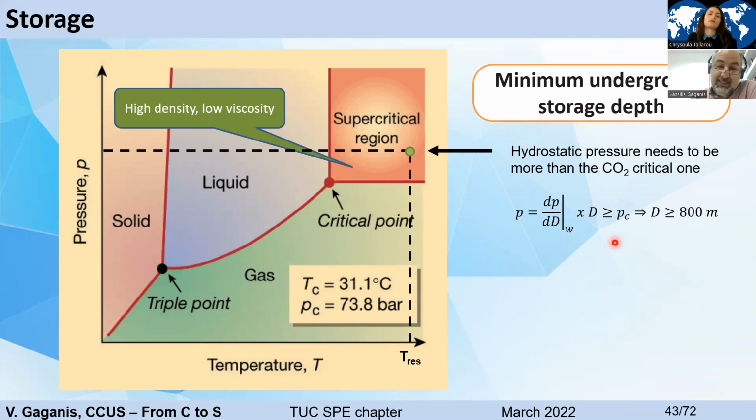But dense at high temperature cannot be achieved in the liquid phase because the operating temperature is very high. So you're going to be living in the supercritical region. So the question is the following. If we have an understanding of, say, the average density of CO2 at supercritical conditions, what's going to be the depth we need in order to go above the critical pressure?